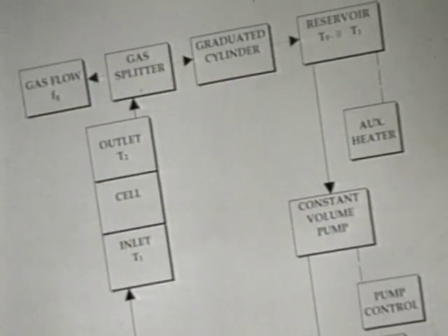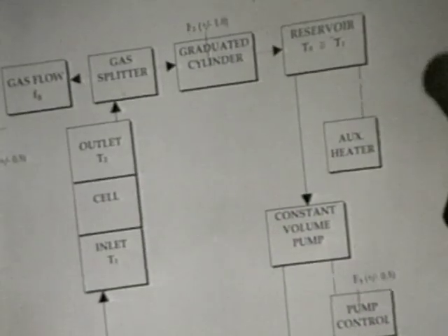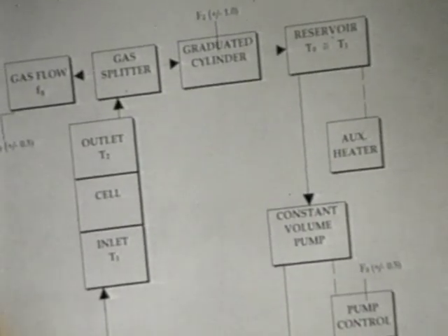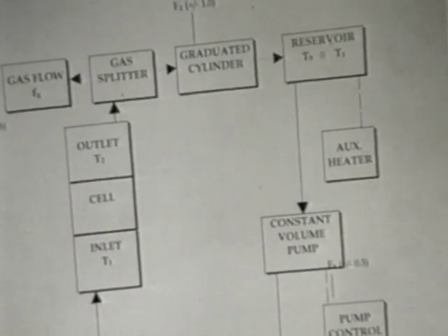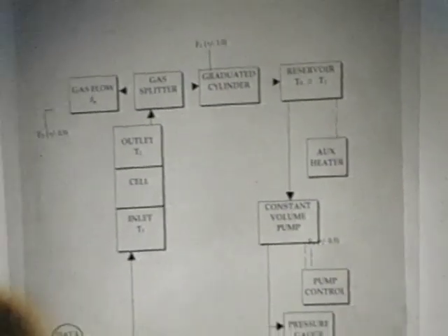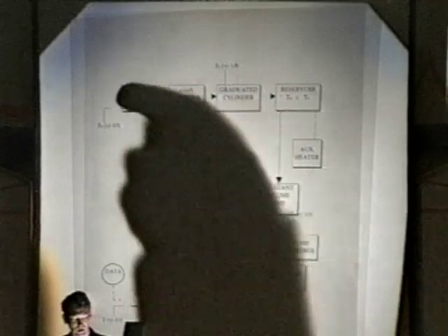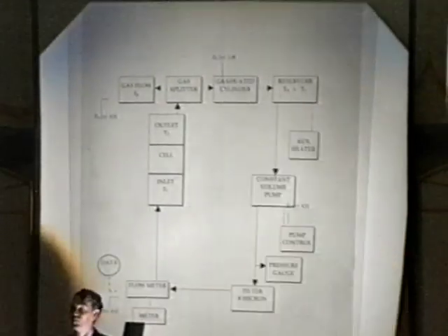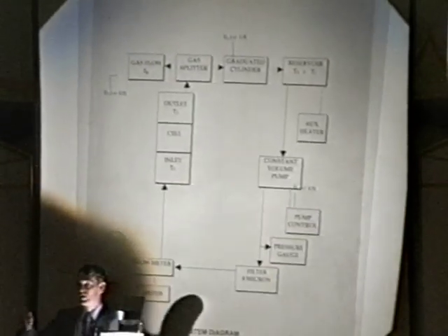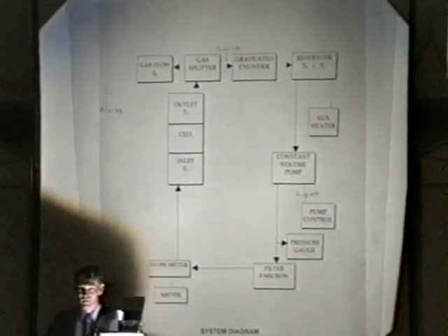Our flow is normally done with a flow meter. It is a little cantankerous because it doesn't like the lithium ions in there sometimes. But we can check that by stopping this gauge and reading the gas flow, and the old-fashioned way of a stopwatch and the graduated cylinder, turn the stopcock and measure it that way.